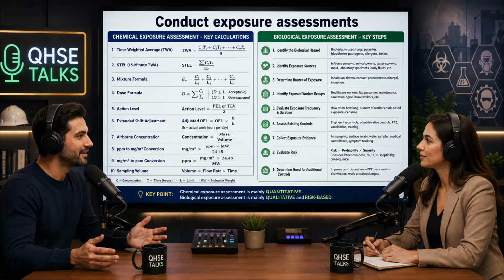All of this incredible math, the TWAs, the mixtures, the noise logs, the APFs, it all relies on one massive assumption. It assumes that the number we plug into the formula is accurate. How do we actually capture that number? How do we trap the chemical and measure the physical reality of the factory floor? We rely on the American Industrial Hygiene Association's 9-step exposure assessment model. It's a cyclical, continuous improvement strategy. What are the steps? The steps include establishing a basic characterization of the workplace, assessing exposures, gathering data, evaluating that data against the TLVs and PELs we discussed, and constantly reassessing as processes change.